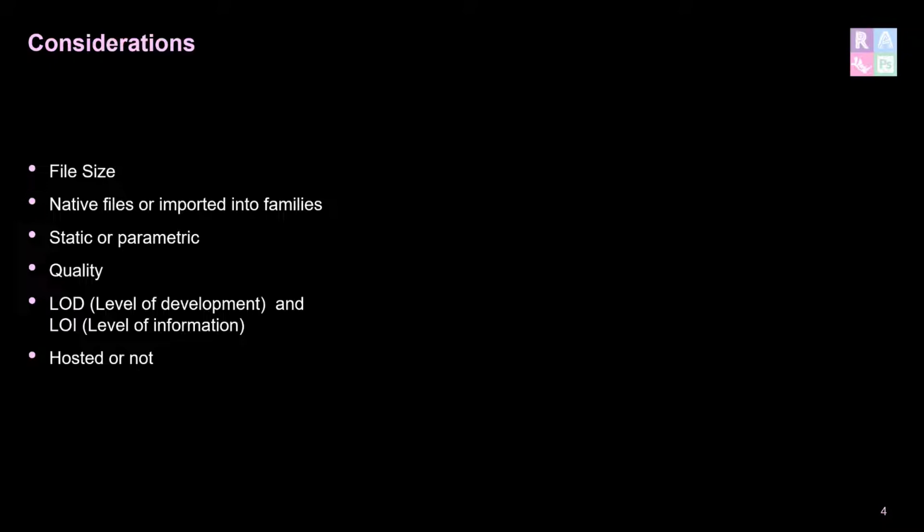That's a hosted family. Say, for instance, a floor is not a hosted family within itself. You could delete the wall and the floor would still exist. But there are families that have to be hosted to floors. So I think one of our families is a fridge, and the fridge cannot exist if it doesn't stick to a floor, as an example. So that's what hosted families mean.